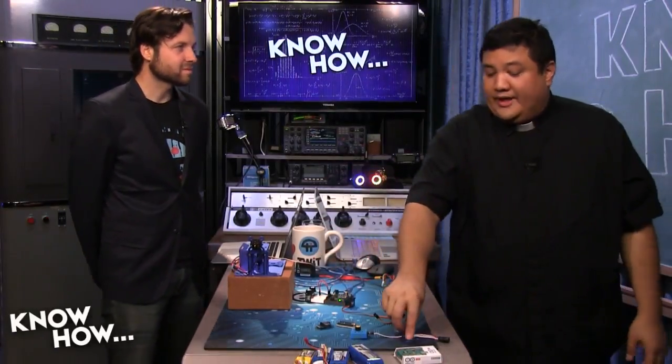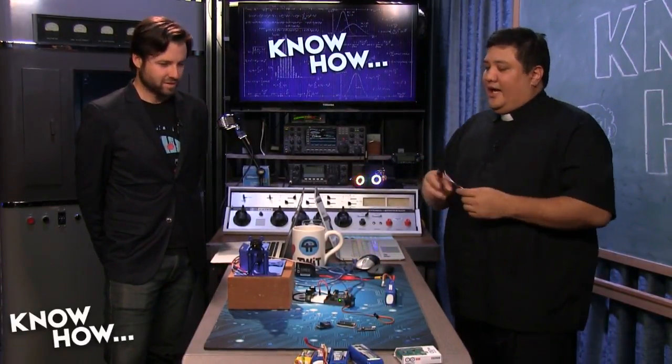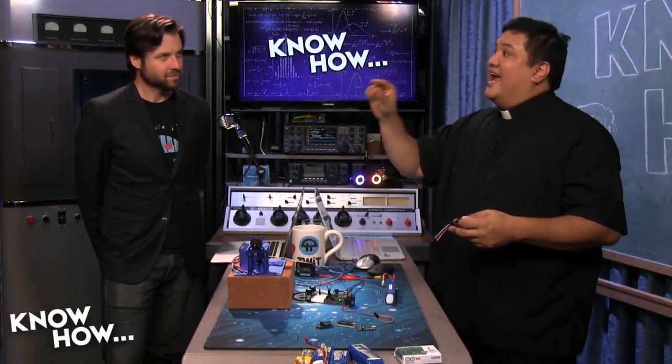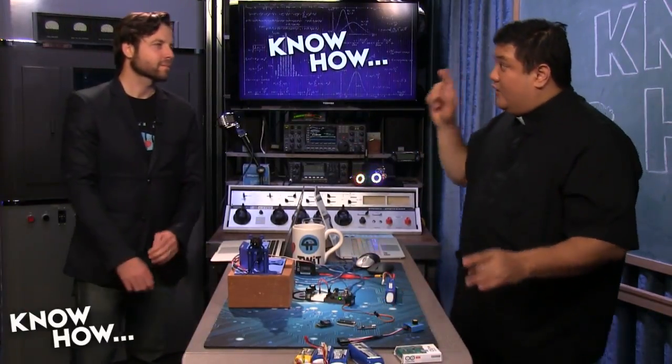Exactly. And now not only am I doing what this did, but I can actually do it with way more precision. I could open up a serial console and reprogram this so that it sends me exactly the value that it's sending. Right. The other nice thing about this is you can find out where your ESC is set. Is it set to start as soon as that value gets to 1,000? Or does it wait until it gets to 1,200? And then it will tell you whether or not you have to recalibrate your ESC. Okay. Yeah, that's handy to know.